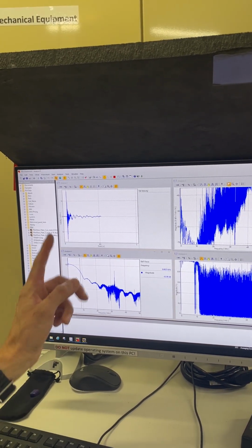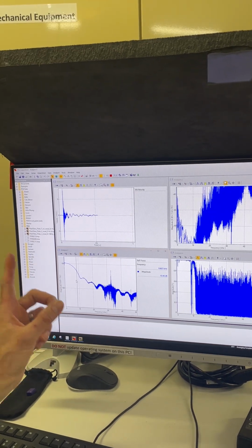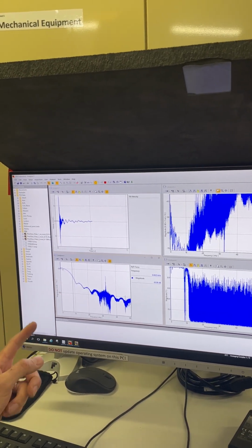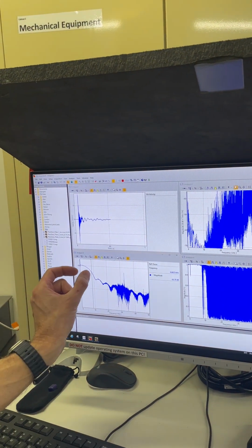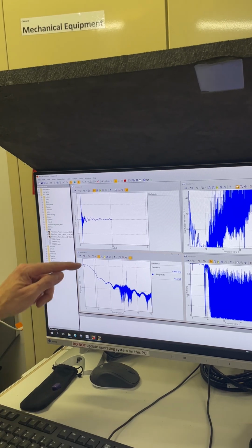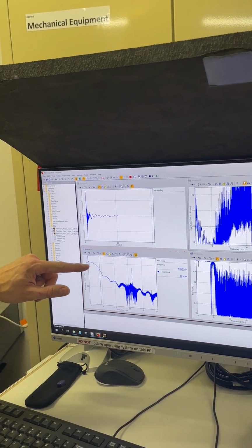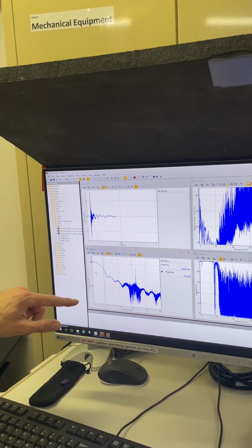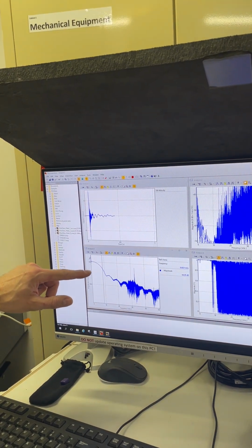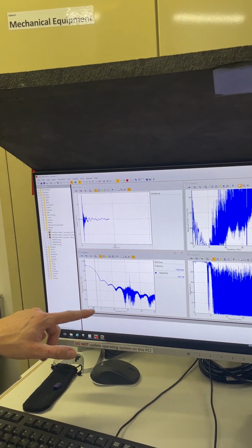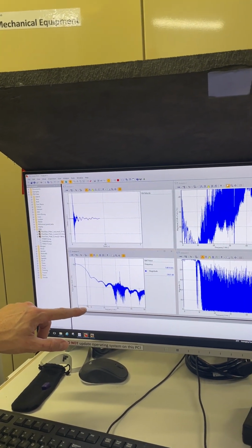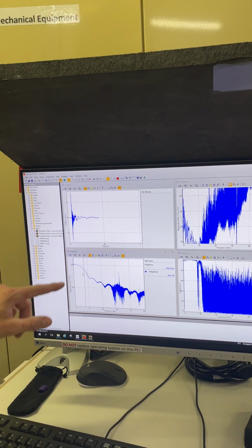For something that's not perfect, so it's got some width, we see this characteristic shape, this sort of lump shape of hills. And this is the useful bandwidth in here. So approximately 1 decade down from the maximum here is our useful available bandwidth. So we've got quite a large scale on here, but if we were to measure up to around about 7.5, 8 kilohertz, this would be a pretty good useful range.